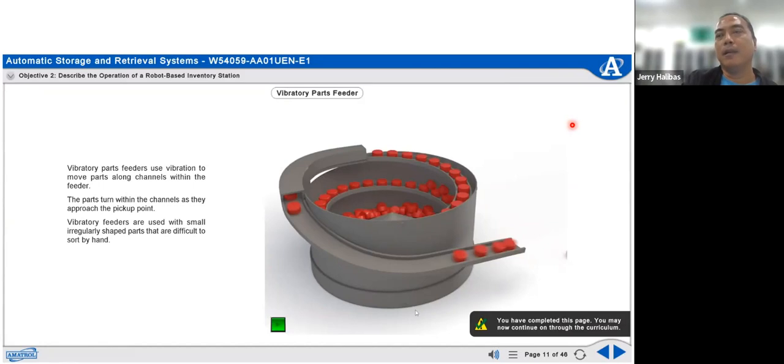Okay, so with the variable frequency drive, you can set the accelerating time or ramp up time, or decelerating time or ramp down. Sometimes VFDs use different keywords and commands, but they are similar.